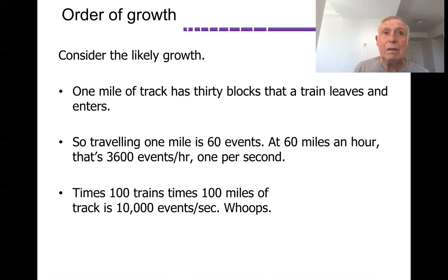I did run into a system once that had a very small number of items that it needed to track. It was a dozen. I mean, it was nothing at all. So what it did was poll each one of the sensors and just ask, what are you doing? What's your temperature? What's your pressure? What's your this? What's your that? And it carried on doing that, and it worked out until we had 24 sensors, and then 200, and then you can see where this goes. It doesn't work. You have to go back to an interrupt.